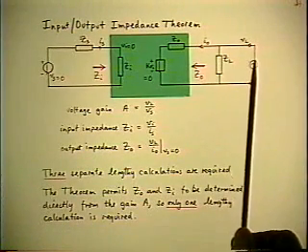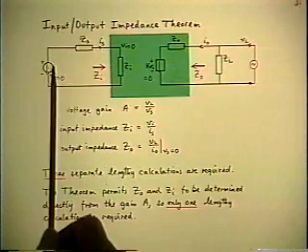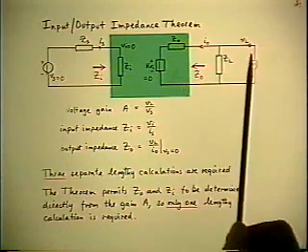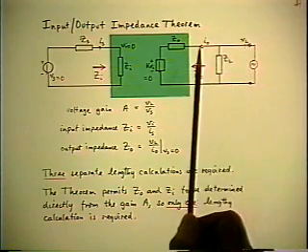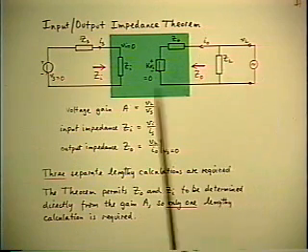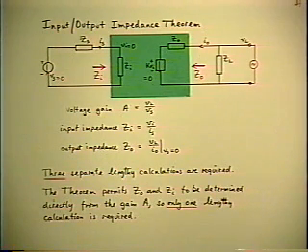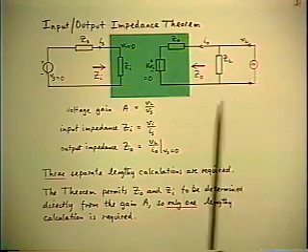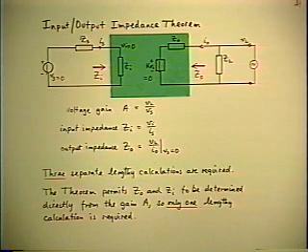To calculate output impedance, the way you usually go about it is you make the input 0, you apply a separate source at the output, and you calculate the ratio of VL to IO under conditions of zero input. That's basically the definition of output impedance. And especially if there's feedback in the system, again, this is just about as much work as the first two calculations. And so you end up doing 3 separate chunks of work which are more or less equally lengthy.